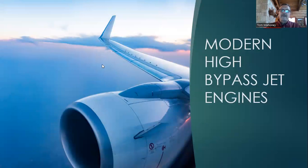What we'll be talking about in this class is high bypass jet engines. This is what most commercial airliners are using today. These jet engines aren't pure jets. Most of the air that is used to create thrust is what we call bypass air, and a percentage of it is what we call core air, which is actually the working air. We have another word for this. It's called fan jets. They're just high bypass jet engines.